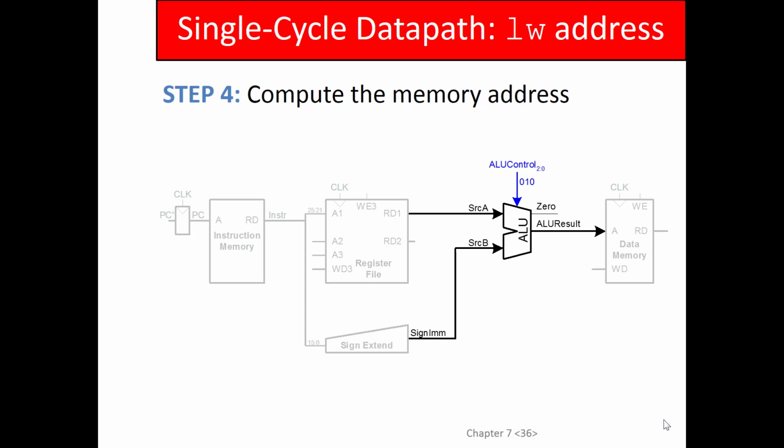And then the ALU result feeds into, now you would think this would feed back into the register file, and it does, except this example is a load. This is a load/store example. So in this case, the ALU result goes into the address input of the data memory, because the ALU is calculating the effective address. You're taking the source and adding the offset, and using that as your effective address for a load or store.